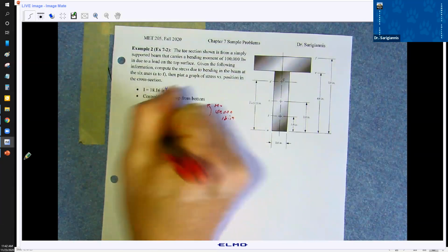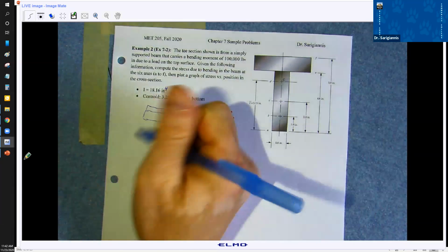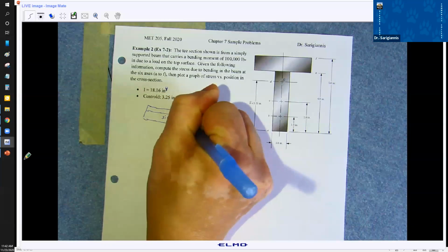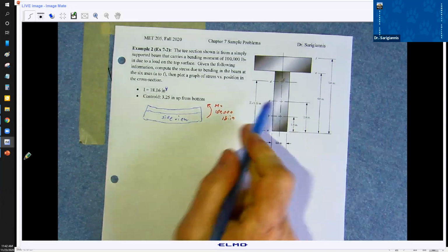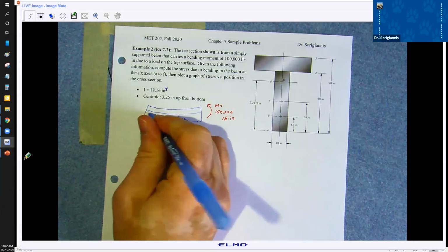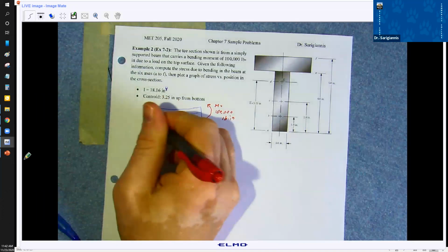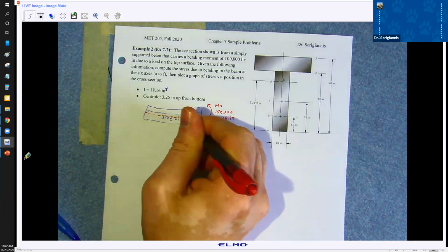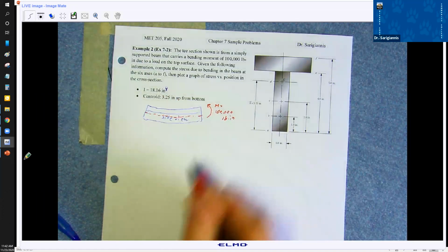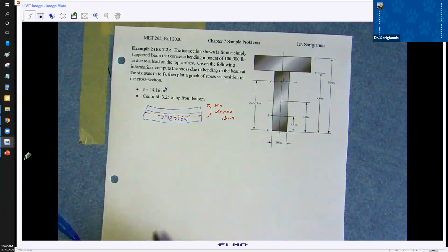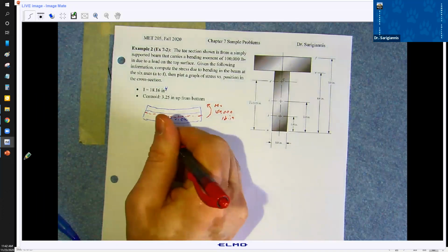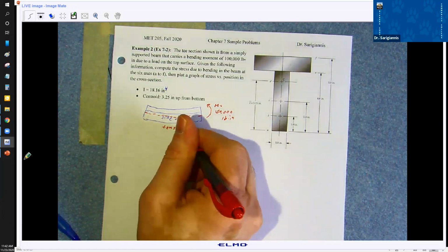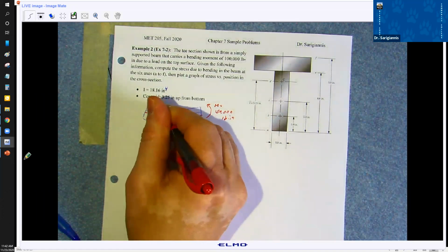So this is, let me just label this side view. Now your centroid, draw it in red here, runs through the beam like this. This is your neutral axis. So down here, we're in tension. And up here, we're in compression.